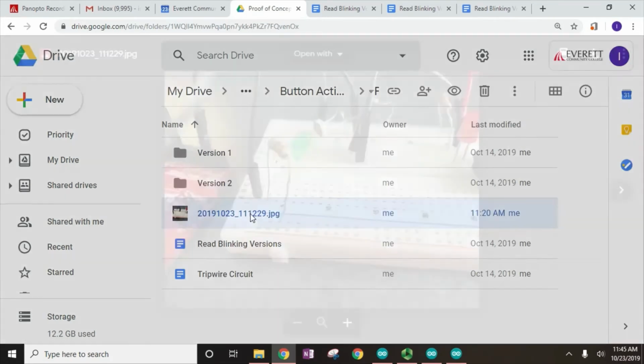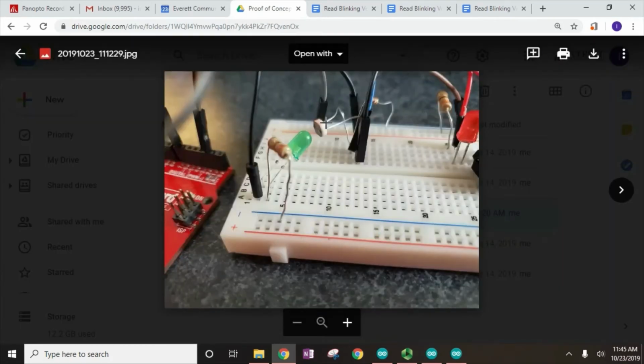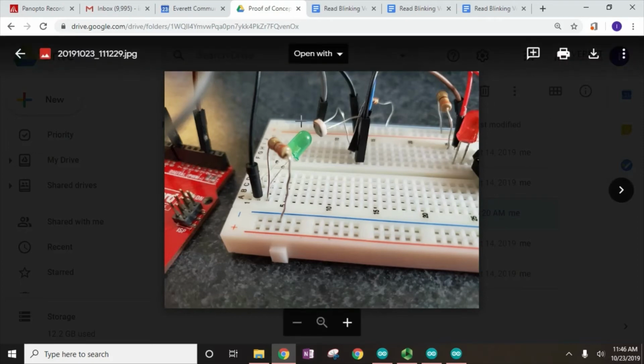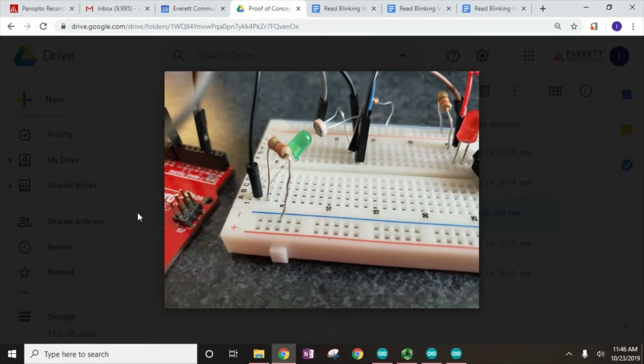The tripwire is, I have a photoresistor and I have an LED. This LED is going to be on constantly. And so it's reading this really high light because it has an LED pointed right at it. And if I block it, it sees that something's blocked, and it will send a signal. If my alarm is also on, then my alarm goes off.